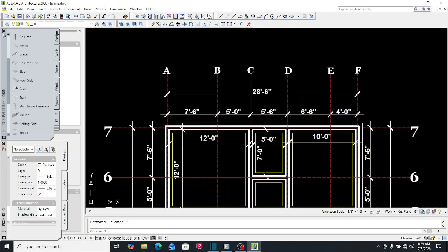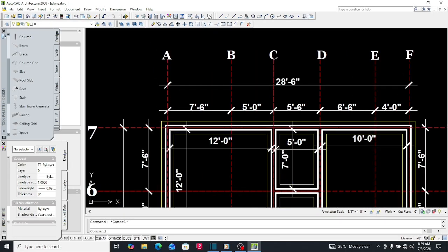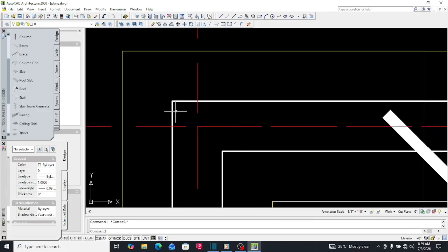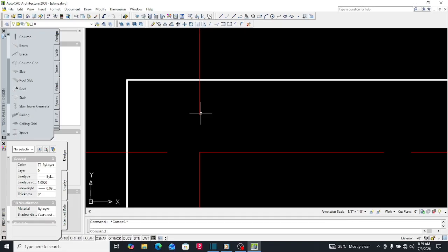So you're going to fix a nail on the board. Then you pull from the nail that you just hit on the board. You are going to measure 3 inches left and right. 3 inches to the left and 3 inches to the right. And also you have to fix a nail over there. You get 3 inches left, 3 inches right, you get 6 inches, making the block. And then you can stand on the same nail, that is the initial nail.